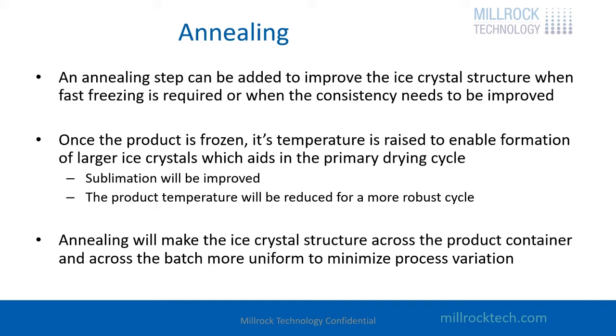So once the product's frozen, the temperature is raised, larger ice crystals are created, and that enables an improved sublimation rate. It's also going to protect the product better, because the product temperature is going to be reduced during the primary drying cycle. So the annealing will make the ice crystal structure across the product container more consistent and across the batch more consistent.